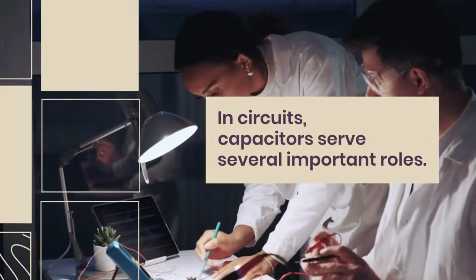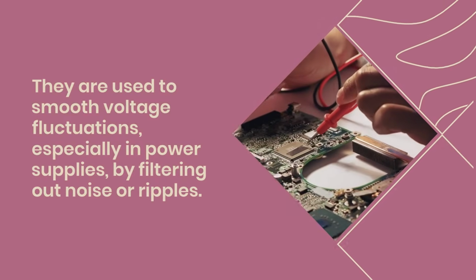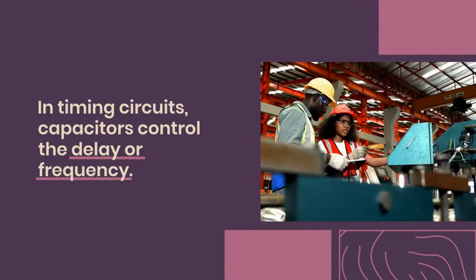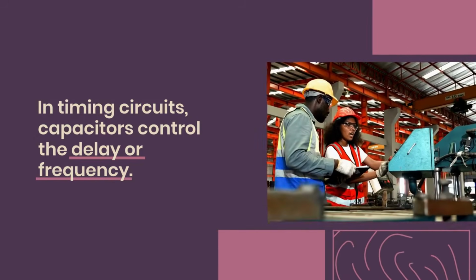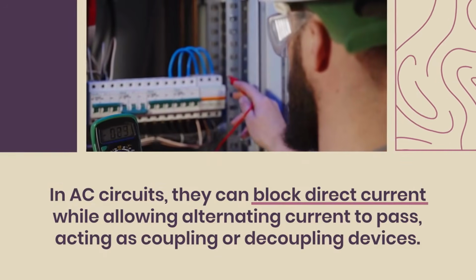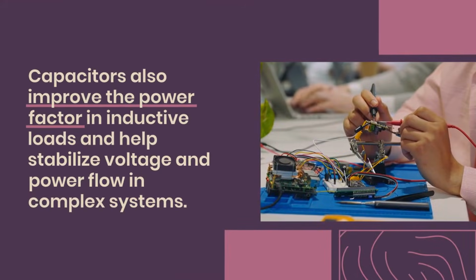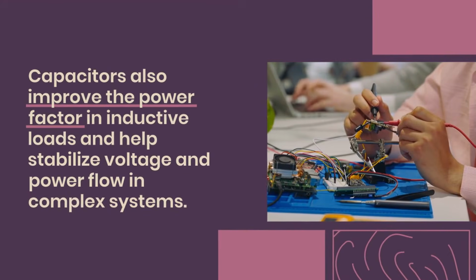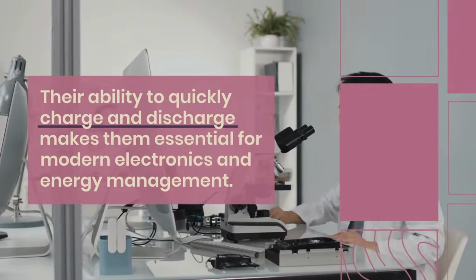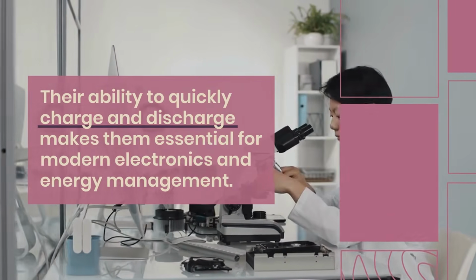In circuits, capacitors serve several important roles. They are used to smooth voltage fluctuations, especially in power supplies, by filtering out noise or ripples. In timing circuits, capacitors control the delay or frequency. In AC circuits, they can block direct current while allowing alternating current to pass, acting as coupling or decoupling devices. Capacitors also improve the power factor in inductive loads and help stabilize voltage and power flow in complex systems. Their ability to quickly charge and discharge makes them essential for modern electronics and energy management.